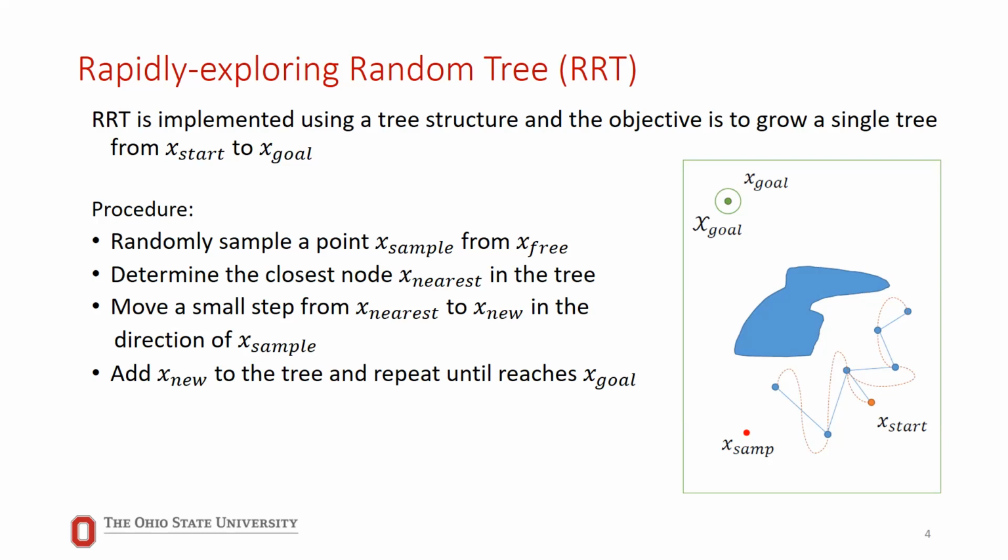Then if there are obstacles, it will avoid them. So now the planner will find the shortest path, right? Because between this sample point and this sample point, you can't find any other direction. It will find the shortest path, which is a straight line. Now, if you have an obstacle, it has to go around the obstacle. We'll see some examples and see how it deals with obstacles. So when we have a new X, the next point is our goal until we reach the actual goal. Here you have to start from this start point and find different ways to get to this goal.